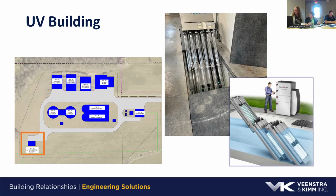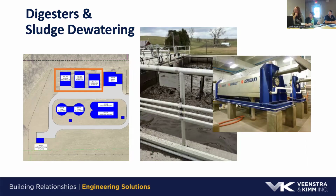And then finally, the digesters and sludge dewatering. As far as the process goes, this is kind of a side stream. So in those clarifiers, we settle those solids out. The solids go to the digester, where we add a lot more oxygen and try to let those basically break down and kind of eat themselves, use themselves as food. That stabilizes them, and then we'll send them through that sludge dewatering.